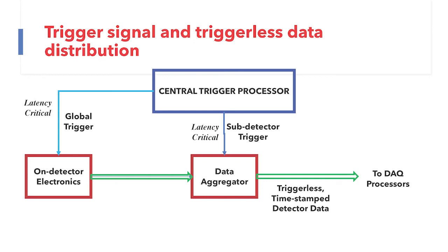And so there are different types of detectors depending upon the particles that are there, and those are all put together near the collision area. And to the on-detector electronics, this global trigger is sent. Now what this global trigger says, it actually sends a window. When it receives a window or a pulse signal, it tells the detector electronics, okay, now open the data capturing window and take data and release the data.